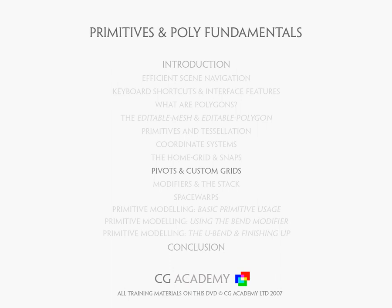Then we'll be moving on to looking at pivots, and those work together hand in hand with the coordinate systems and the home grids and everything else. So yet again, a very key concept. I just wanted to make sure that you have a very good understanding of what the pivot is, what it represents, and how you can change the pivot, because you can modify the pivot. And we also look at custom grids in this chapter, which allow us to create our own, as it were, home grid, which we can build objects on. We can change those at will, and we can have multiple custom grids. So it's a very flexible feature in 3ds Max, and something which is worth looking at for certain modeling projects.